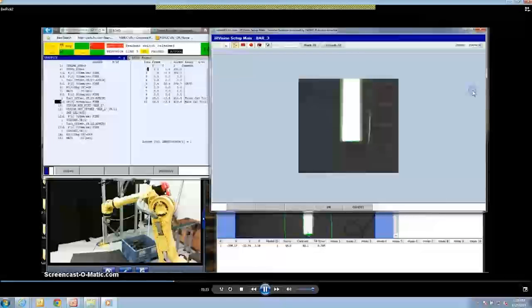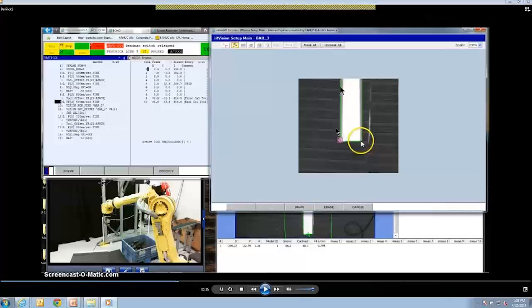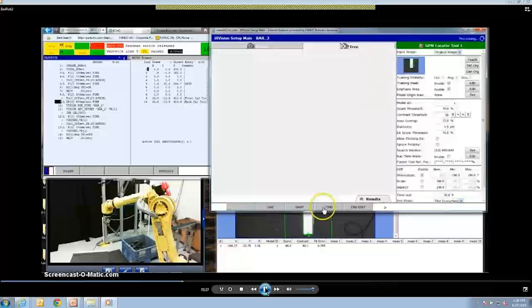And then what I do here is I use an emphasis area. Since there's not much information, there's a big edge here and a big edge here, not a very big edge here. So this edge is not a very big part of the pattern. So it'll find enough of these edges, and it'll end up drawing this edge anywhere, because we're asking it to find only 70%. Our score threshold is set to 70%. So finding both of these lines is probably like 80%. It'll just draw this line arbitrarily anywhere, so I can't see it. But by setting this line as an emphasis area, we're saying you need to find 70% of the whole pattern and at least 70% of this line as well. That's the beauty of the emphasis area. That's with the blue. So now we got a good pattern.